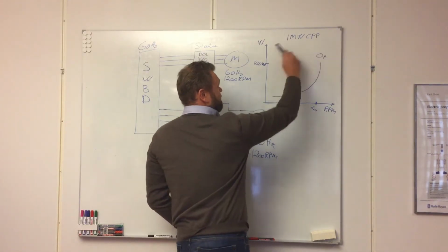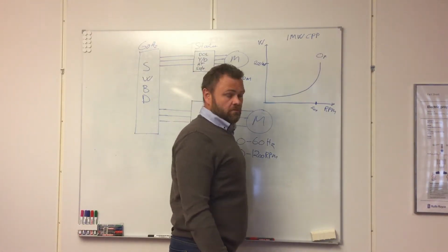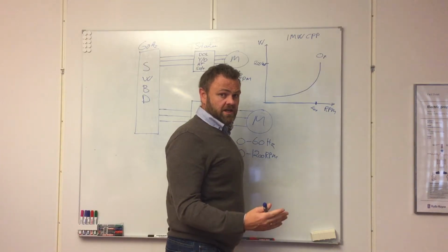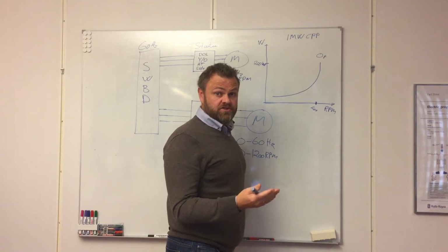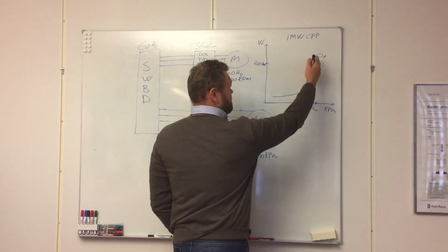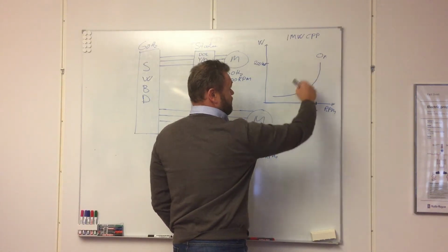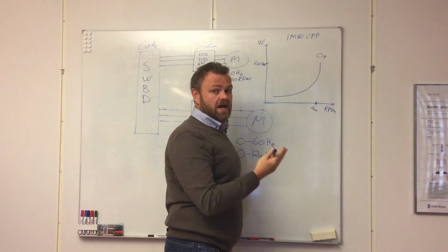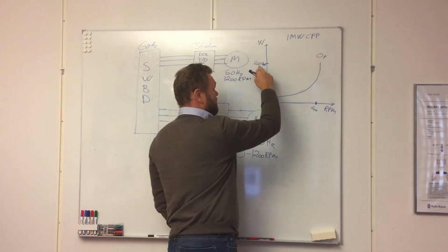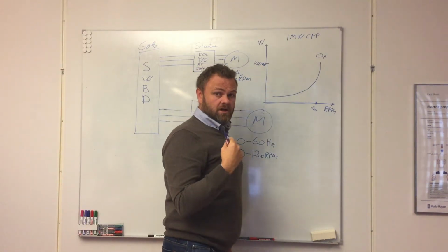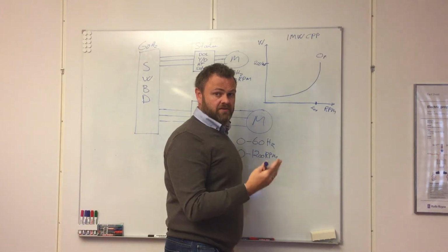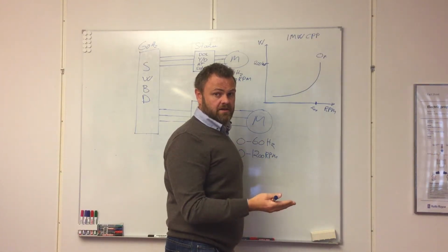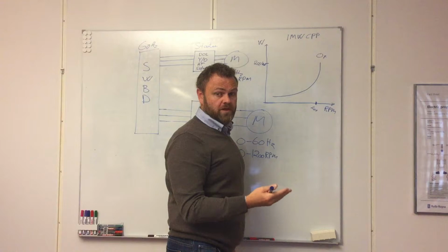So this 1 megawatt controllable pitch propeller running many hours, maybe at zero pitch or close to zero pitch, you will have 200 kilowatt just to have this propeller running and ready to be used.